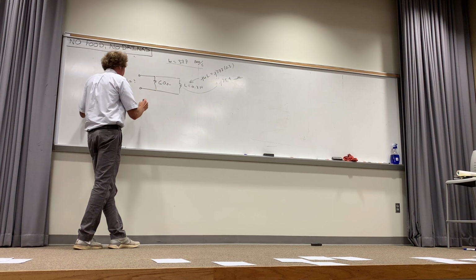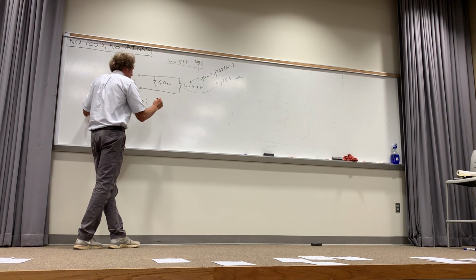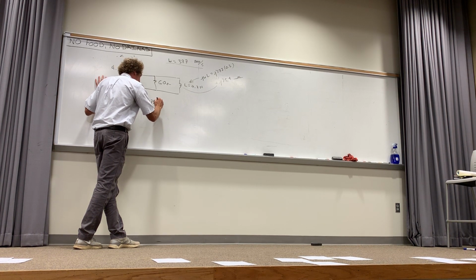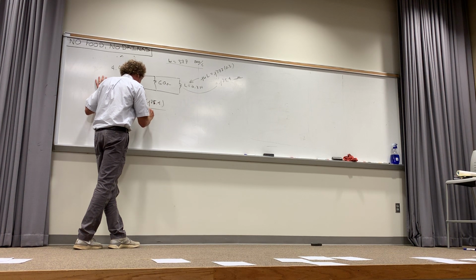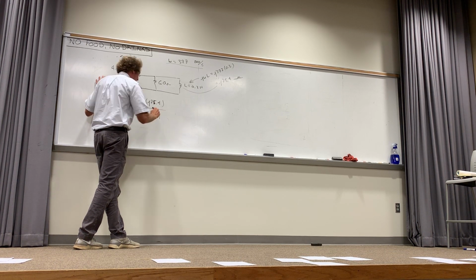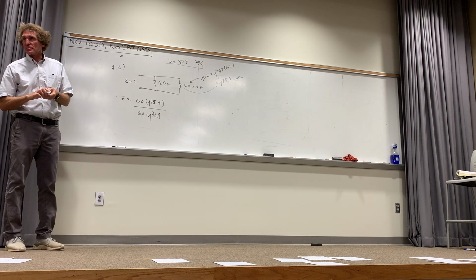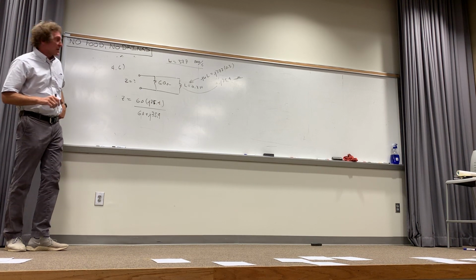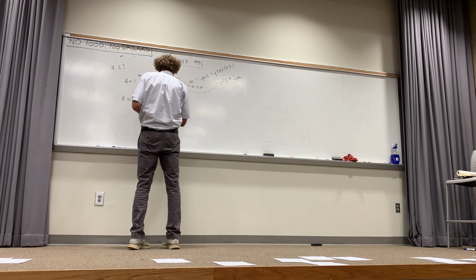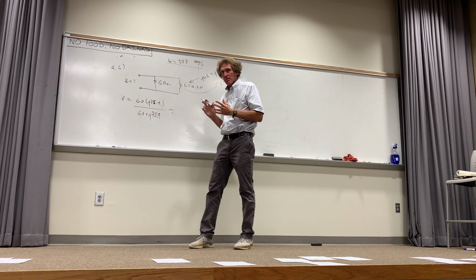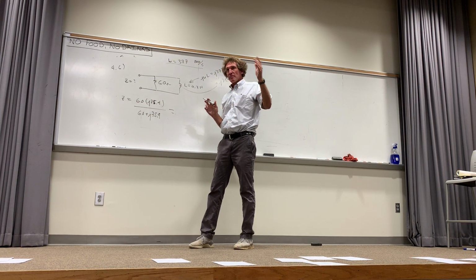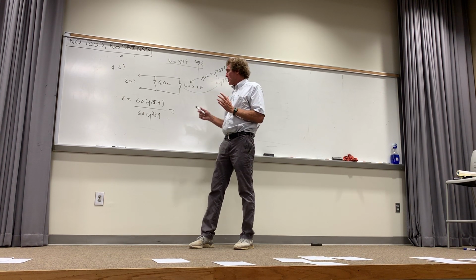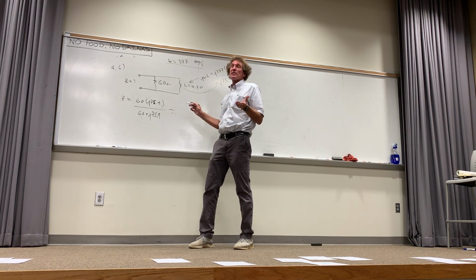I'm going to multiply 60 times J 75.4 over 60 plus J 75.4. Again, I'm just treating these as I would resistors. You do it exactly like that. Are you with me, class? Now, look at this. What do you get for this? I'm going to get a complex number, correct? I could have a real and an imaginary component, or I could have a magnitude at an angle, couldn't I, class? Can somebody give me this in terms of a real and an imaginary part?